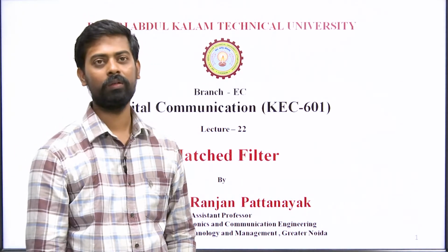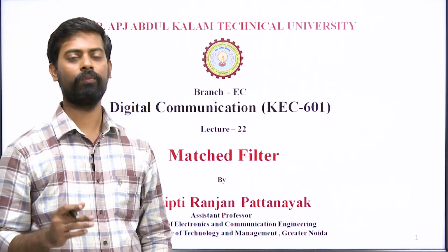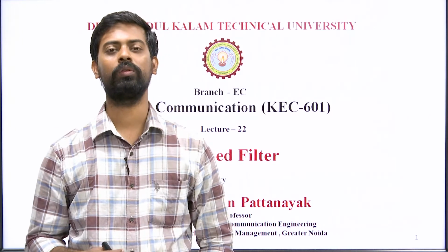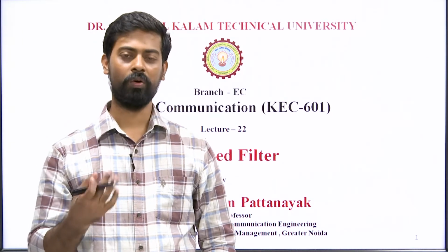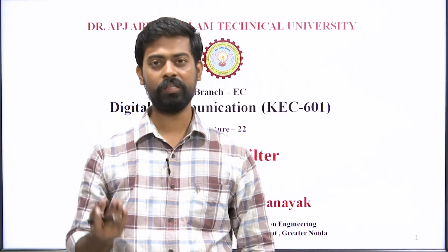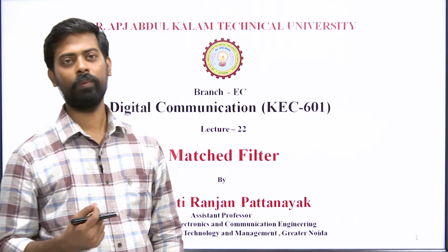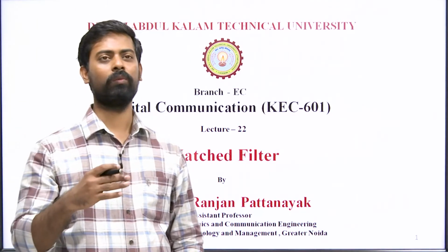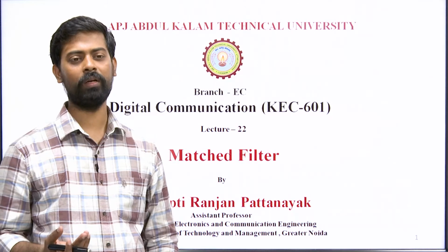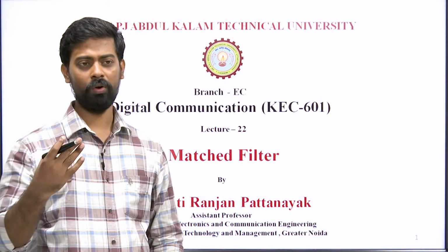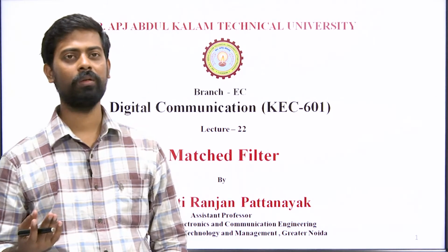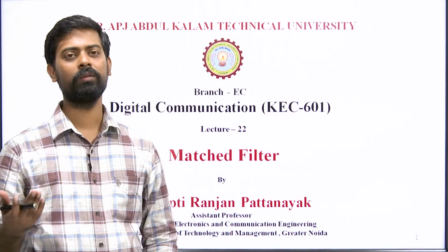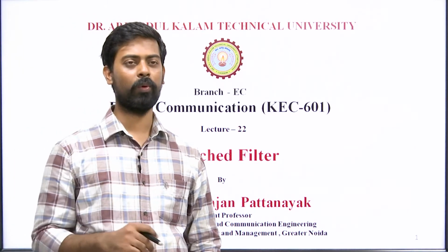Today we will see the matched filter. In the previous lecture we already read about the optimum filter, which is used to extract the desired signal from a noisy environment. The matched filter is nothing but an optimum filter when your noise follows white Gaussian noise, and the purpose of this filter is to increase the SNR and decrease the probability of error.